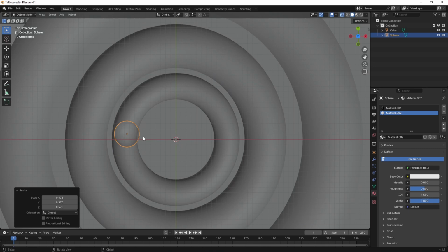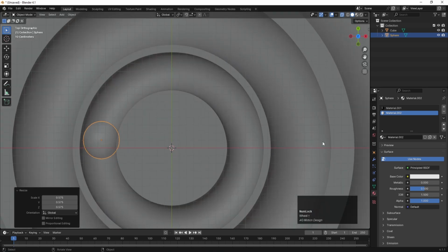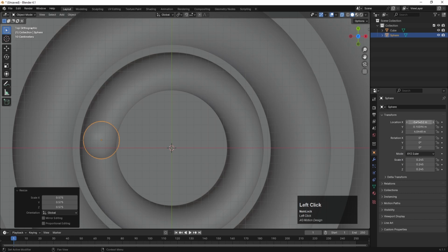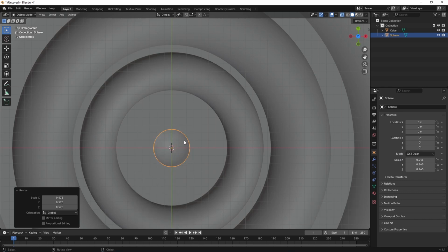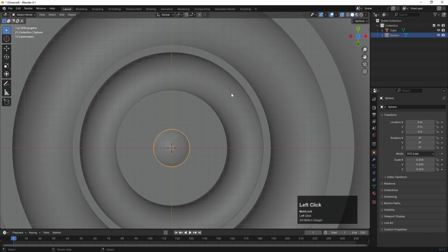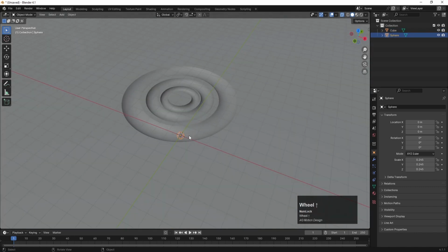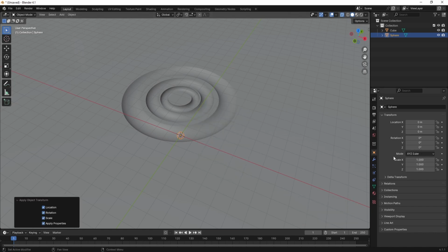Okay, but if you see properly over here, it will create some problems for animations. So instead of doing that, let's go to the transform object properties over here, and we will change all the positions to 0 like this. Sorry, let's select this object over here, hit Ctrl A, and we will choose all transforms, so all the scale properties are properly applied like this.